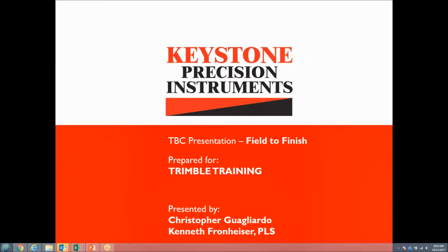So on to today's webinar, Field to Finish. We're going to describe today how to create a feature code library. Once that library is in the data collector, you will be able to code your features that you're locating in the field so that you can actually see your line work in the field and then bring it into Trimble Business Center to generate line work.